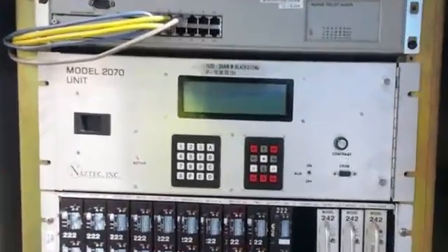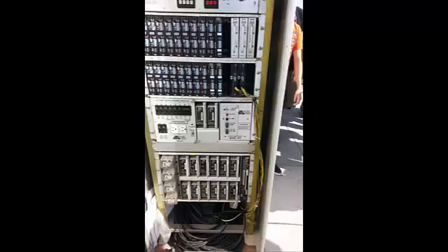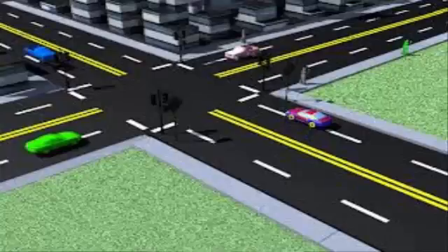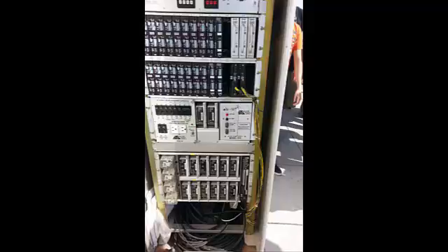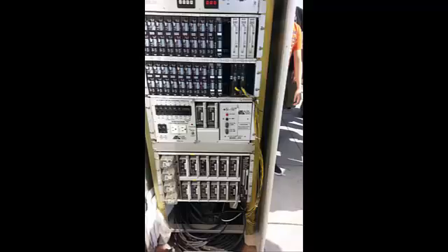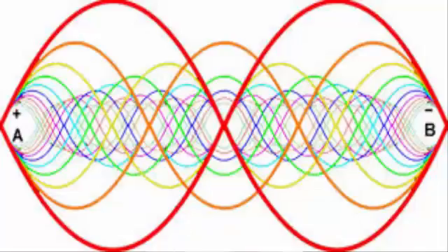The detector units identify vehicle actuations based on information sent to the unit by their associated field units, and they pass this information along to the controller for use in timing the intersection. Detector units are referred to as detector amplifiers when they are used with inductance loops. In addition to identifying vehicle actuations, the detector amplifiers also power the inductance loops, resonating them at a selected frequency.